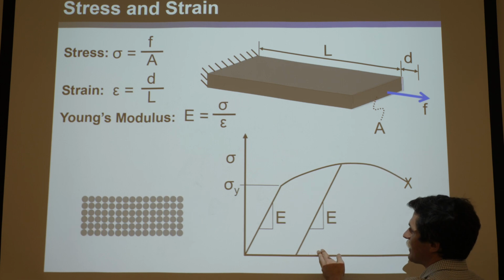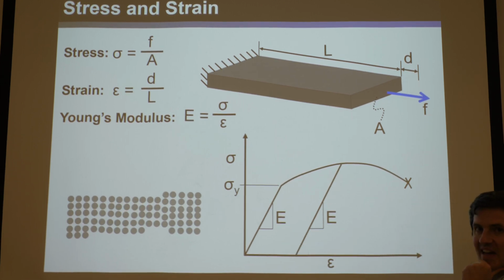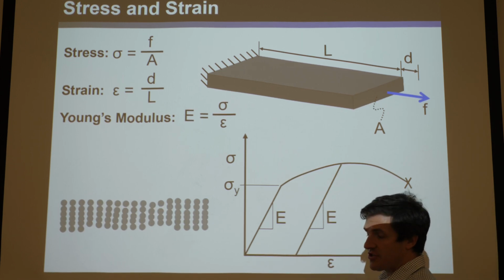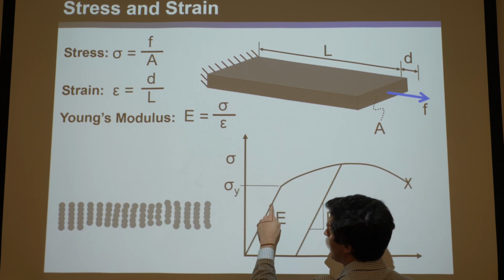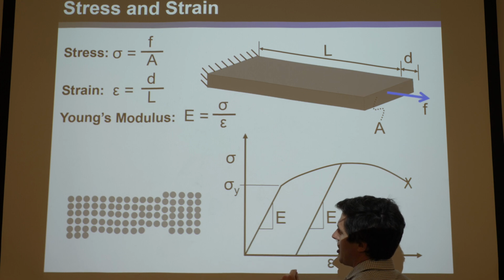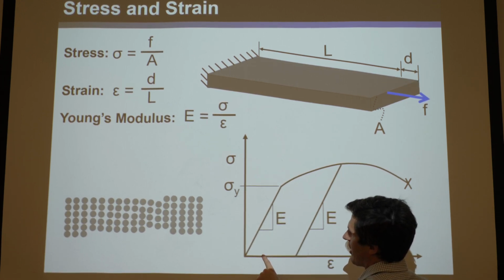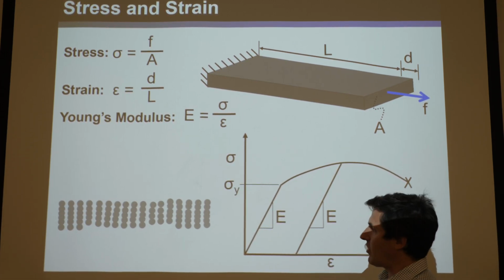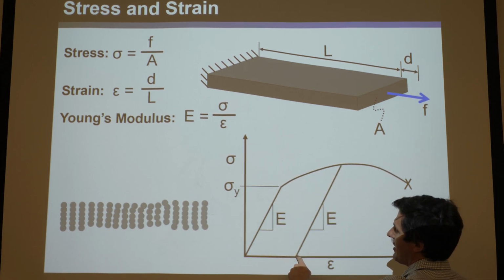The other thing is that they will exhibit hysteresis. And hysteresis means it's now dependent on the history of the loading, essentially. So if before you yielded, you're just going up and down, you don't ever need to know how many times it's gone up and down, because if you're ever at this strain, you know you're at that stress. So there's a one-to-one mapping.